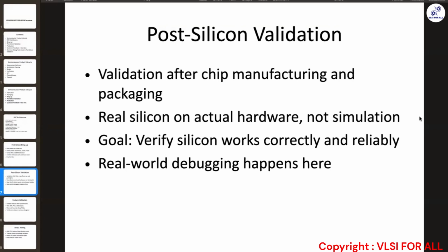Consider you are connecting a Type C display to the port in the Type C interface. The first thing, you plug in, then you open your device manager. Since your Type C is part of your 3.1 extensible host controller, which is sitting on your CPU, you may have to check under system devices, and if it is USB 4, you check the USB 4 controller.